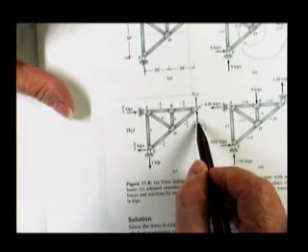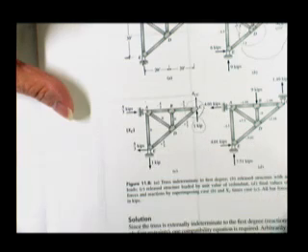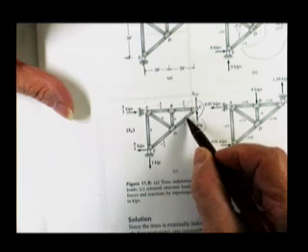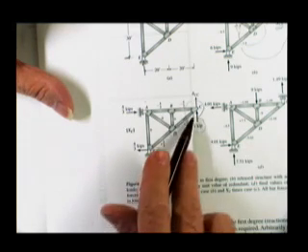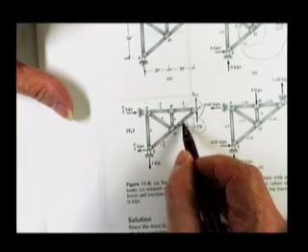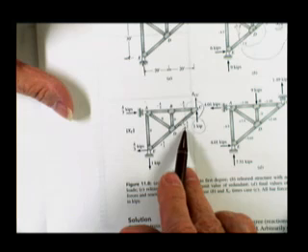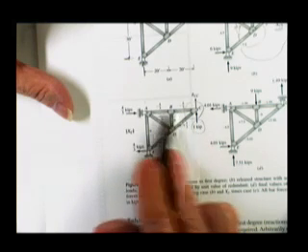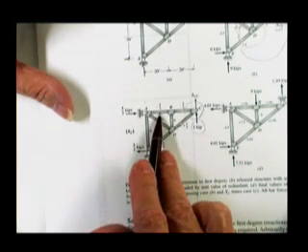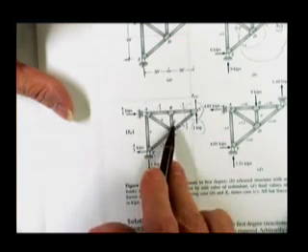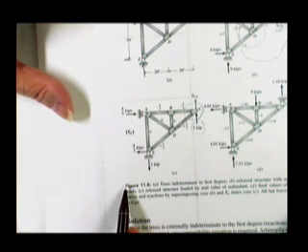So he puts a unit load on here. Again, he probably did a method of joints, plus one up, minus the force in this member down, except not all of it points down, only a piece of it points down. He's going to have to put the slope of the member on there, and he gets a tension force of 5/3. Summing forces horizontal, he gets the force in this member. Coming to this one, summing forces horizontal, he gets this member's force. Summing forces vertical here, he gets 0, that's a 0 force member.